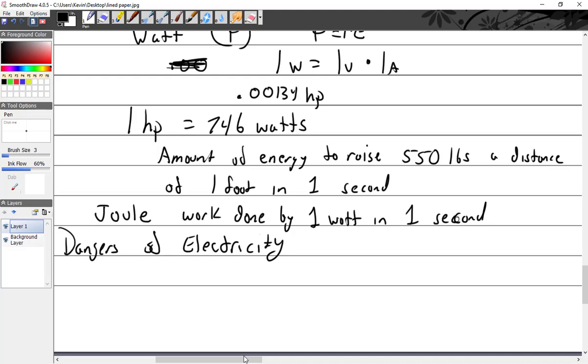Now, I will tell you this, though. Camshafts are the worst. I don't know why, but they have a little coating on them or something. You put it in the clamps, and sometimes you wouldn't get good contact. You hit the button, and it will arc across and shoot out at you. It arcs, and whoa, it makes you jump. So there's enough voltage to jump that, I guess. Anyway, so dangers of electricity. I'm going to move it over here.